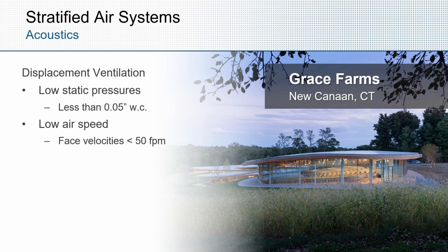If you're trying to provide diffusers in the ceiling or hide them behind the architecture for a fully mixed system, this allows you to tuck them away from sight underneath the chairs and provide a displacement ventilation approach to the space. Again, about every other seat is typical. The round floor diffusers supply around 40 CFM at 0.04 or 0.03 inches of static, which again helps keep the noise down.